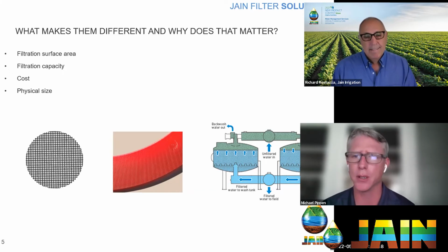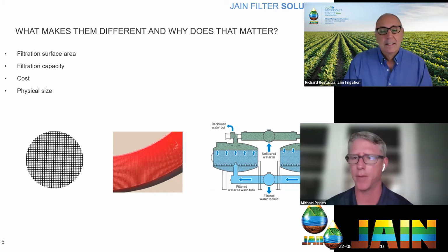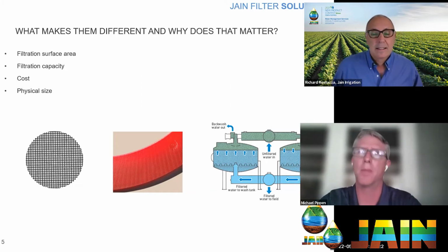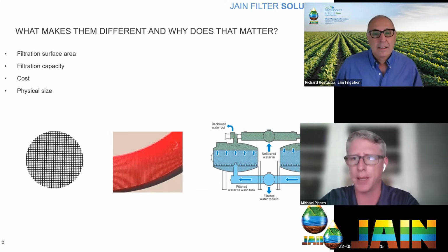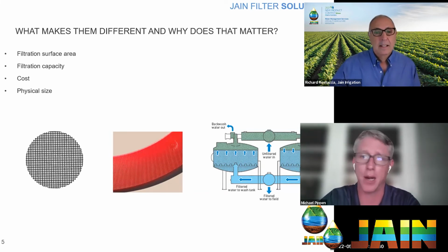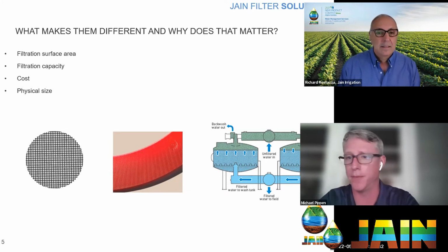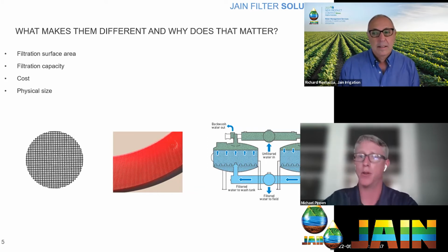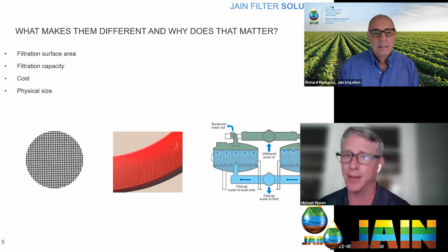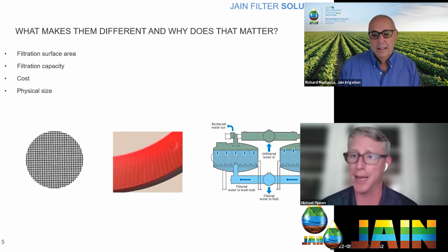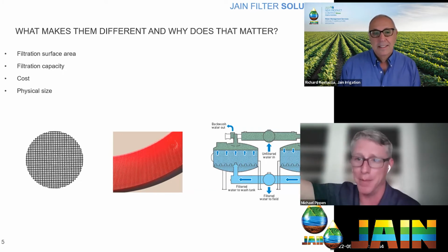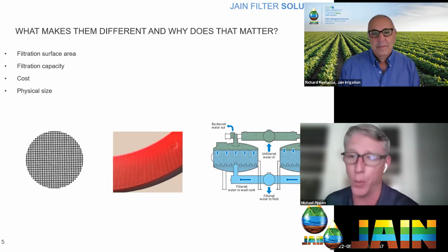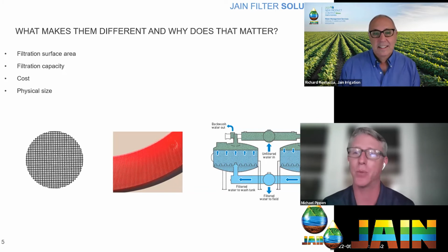And we do pull a lot from our experience as a designer. If I put my designer hat on, especially going into a new application, a new water source that I haven't used there, every one of them is different. Every designer will tell you that. You can have a well, move over 20 foot, put another well in. It might be exactly the same, or it might be exactly opposite. Or you put the suction line in the creek, and it's beautiful the day you're there, and then it rains upstream 2 days later, and it turns into chocolate milk for a week. I mean, those are real live things that I experienced, sometimes the hard way.